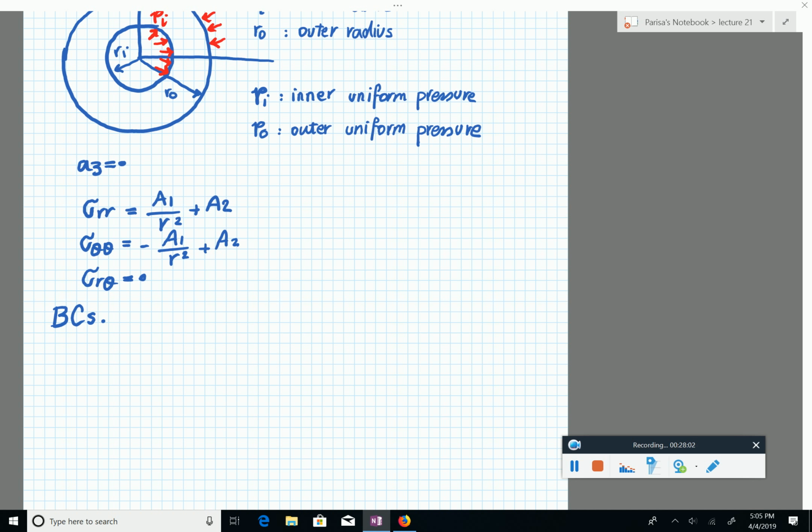Now that I finally graded everyone's homework number 5, when we say boundary conditions, they have to be expressed in terms of displacement or in terms of stress, because our formulations are either in terms of stress or displacement. So you cannot just write the fraction is equal to this. This is not boundary conditions. This is useful to solve an elasticity problem. And this problem you have seen a few times already. So I make the screen blank because I want everyone to write this once.